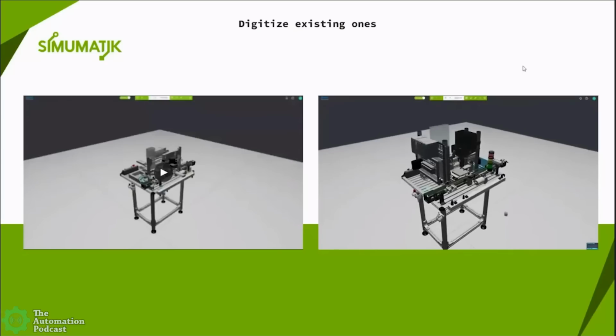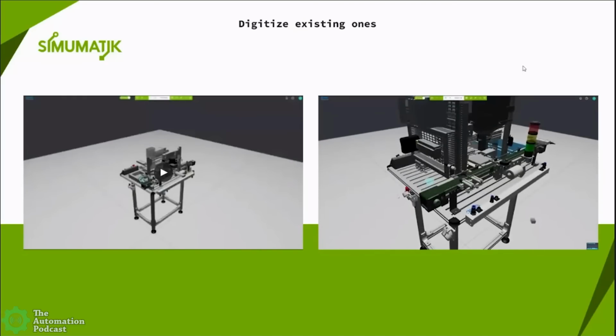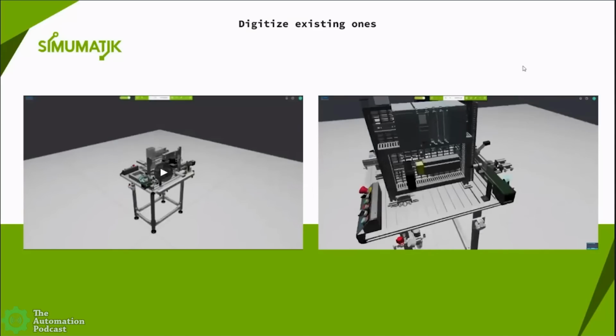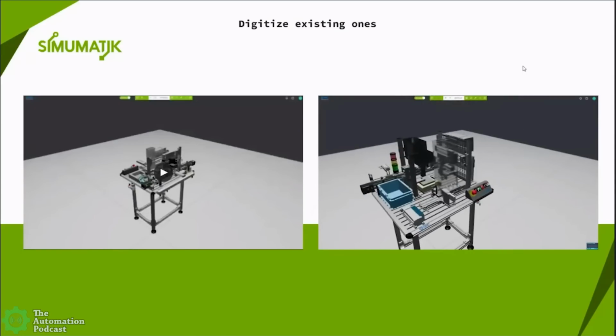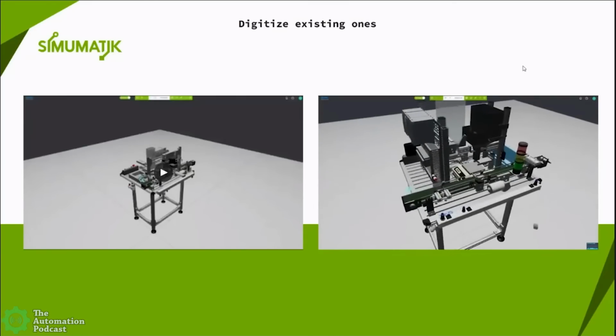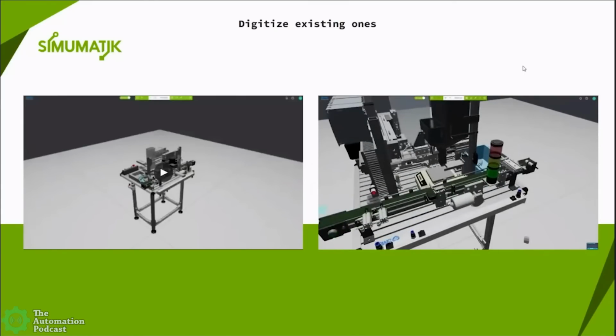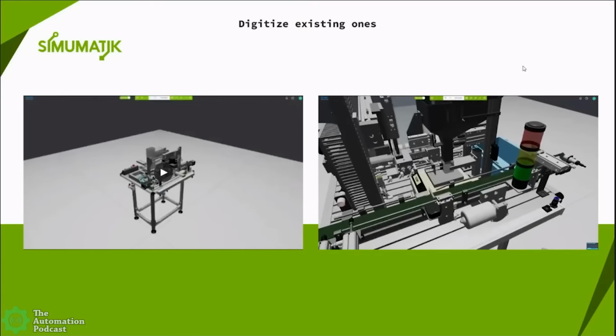But as you know, once you set up different stations together, you can introduce a MES system, plan production, and all this stuff. And basically, for the virtual model, all this is transparent. Even the HMI, if your PLC believes it is connected to a real thing, even if it's connected to the virtual thing, the HMI will work. The MES system connected to different PLCs will believe what the PLC is seeing, so you will be able to change recipes, plan your production, or whatever, and all that against a virtual system or production line. So it offers a lot of possibilities.